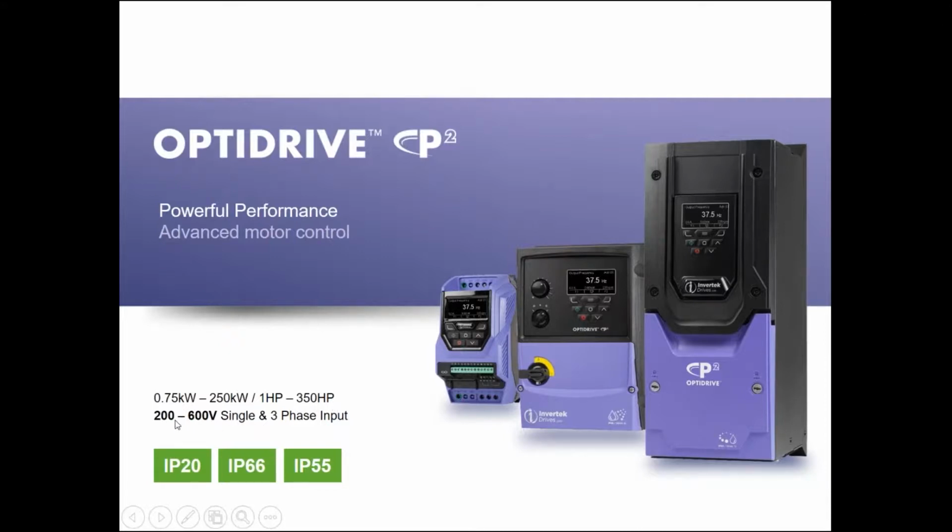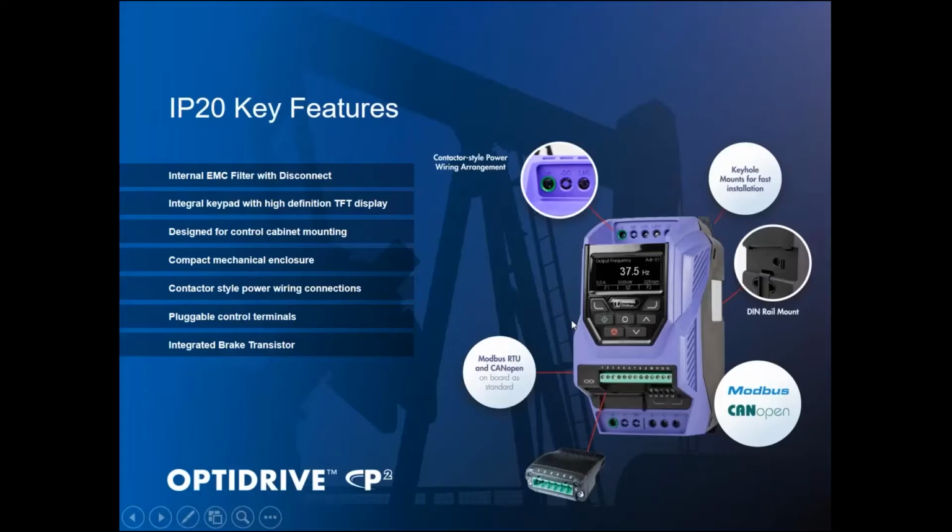And these drives do not have a 110 volts installation, but they will also be available for single and three-phase input. The IP55 drives are only available for this family, for the P2 drives, and as I told you before, this is the high performance drive.